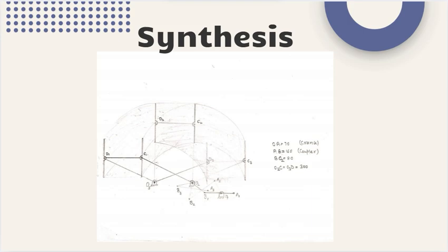This graphical method automatically preserves constant link lengths and ensures correct motion transmission. With just a ruler and a compass, we can validate the sweep, check interferences, and decide final dimensions before moving to CAD or simulation.